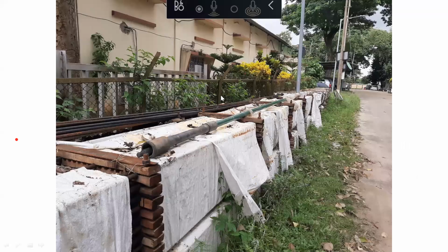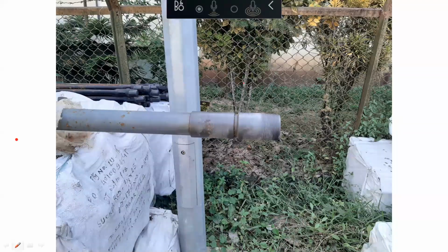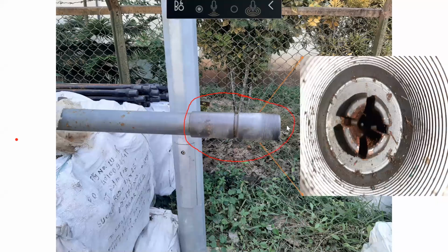Like I said, this is your barrel. Okay, this is your bottom extension. Why do you need this extension? Because you want your standing valve assembly to be located outside your barrel, because your barrel will have a smaller diameter than your tubing pump extension. This will be your bottom extension. Your standing valve will be located here. If you see from the bottom, your standing valve will be located here.